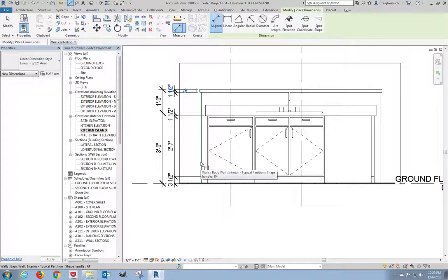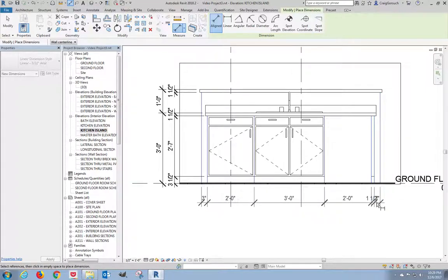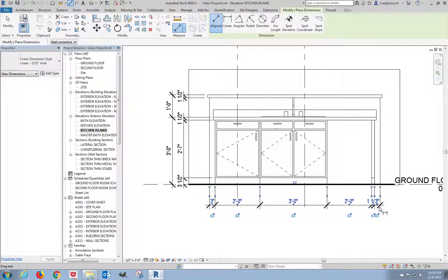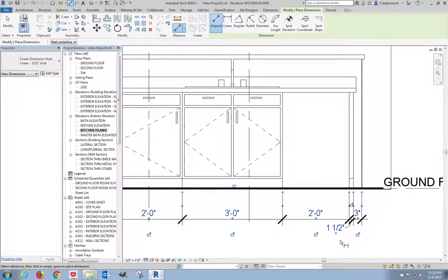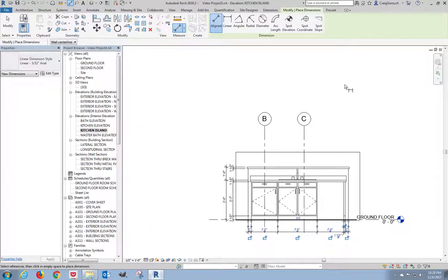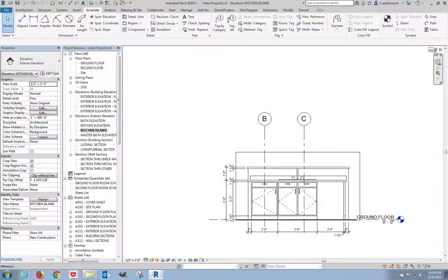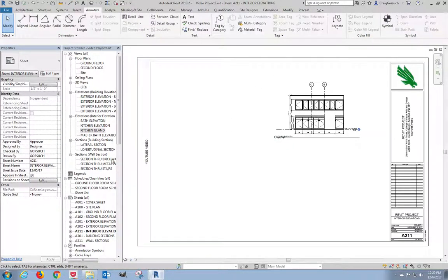And what we're going to do that's a little bit different, from the end of the wall to the cabinet, the hole for the dishwasher, the other side of the filler plate, the other side of the wall. Obviously some things are not reading right there. If I move just this one, it'll give us the best chance for everything being readable. That's better. Modify. Let's close this view.